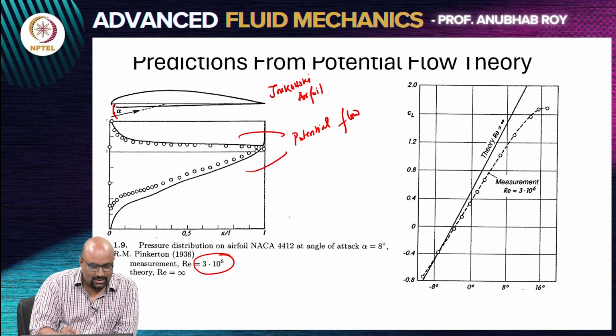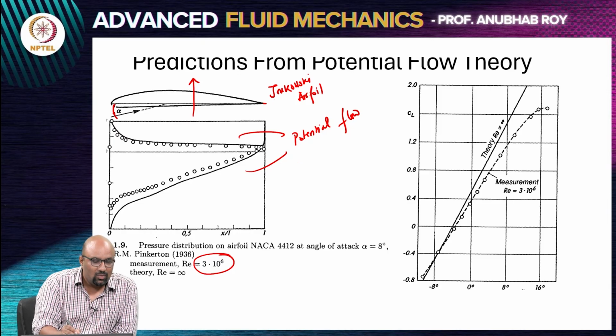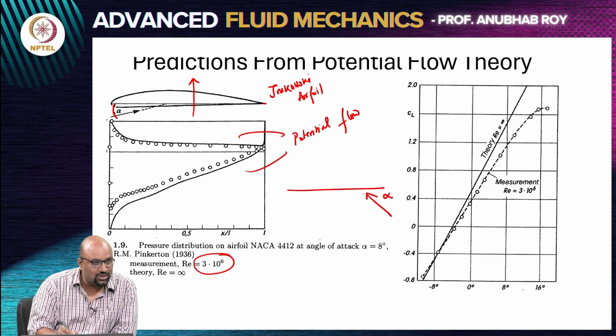And this also brings about the fact that if the pressure forces on the top surface and bottom surface are not exactly the same, you would expect a lift force, which is something we already know. Now here there is a corner with an angle of inclination, and if you remember, we worked out the flat plate problem. For a flat plate, if there was an angle of inclination, we found out that the circulation that it should develop would be proportional to the incident flow times sin alpha.